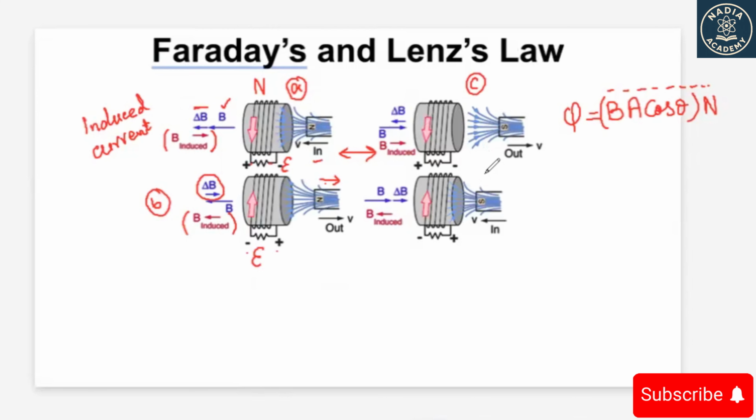And similarly, in panel D of this figure, this is also the same situation as the north pole is moving away from the coil, or the south pole is moving towards this coil. Our induced EMF polarity is the same.